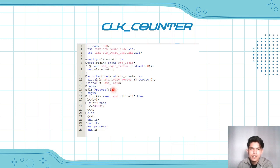The architecture also has a single process P1, which is sensitive to the CLK in input. The process P1 runs when there is a change in CLK in. Inside the process, it has an if-else statement. The if statement checks if the change in the CLK in signal is a falling edge by checking CLK in event and CLK in equal to 0. If this condition is met, it increments the value of the signal B by 1.